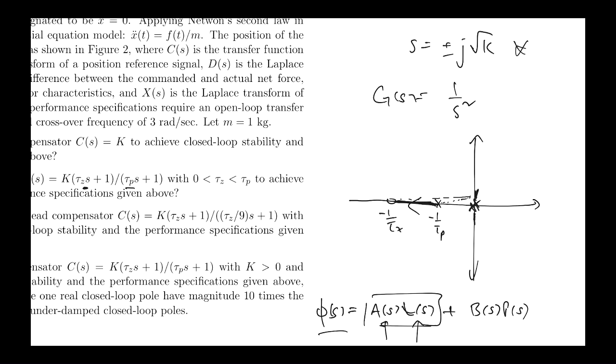And they'll move towards asymptotes that the root locus will approach as k becomes large, right? And those asymptotes are anchored at the sum of the poles minus the sum of the zeros. These are the open loop poles and open loop zeros divided by the relative degree. The relative degree in this case is 2, right?